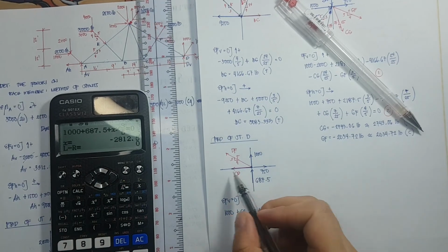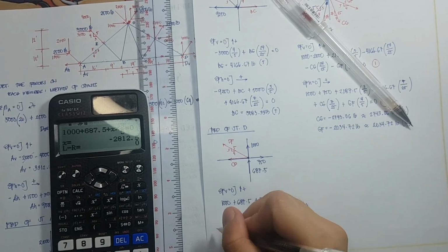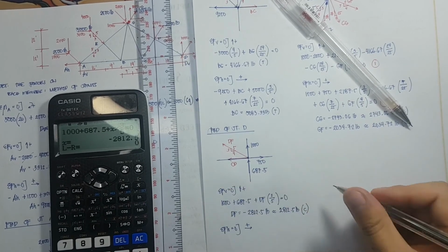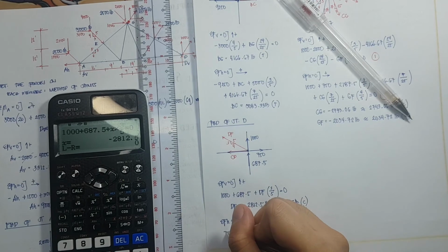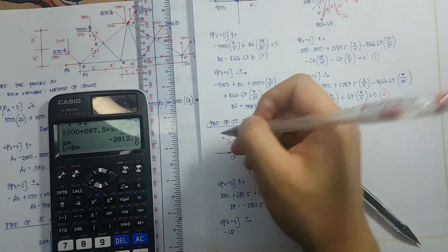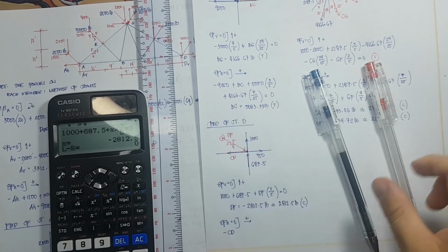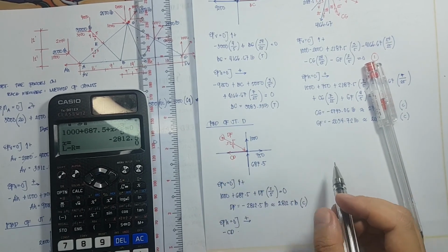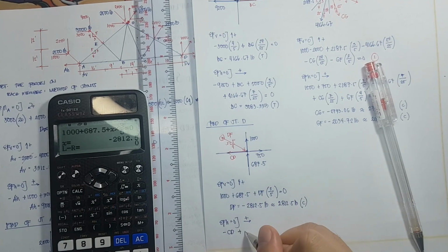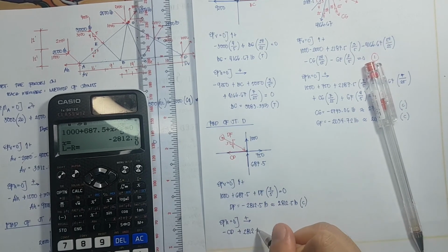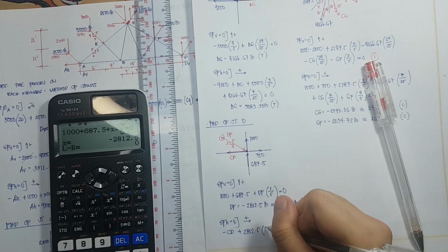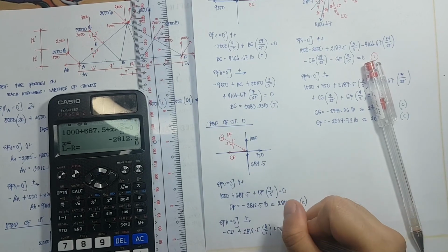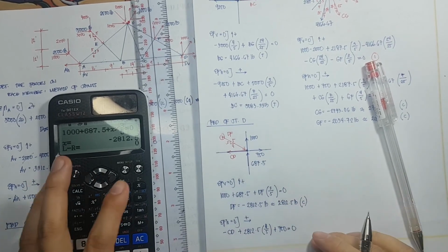Okay, lastly, for the horizontal, for CD, we have summation of forces horizontal is equivalent to 0. All forces that are pointing to the right should be positive. So we have here negative CD. This should be compression. So we have there, what is DF? It is towards right, therefore it is positive, plus 2,812.5 times the horizontal component of 4 over the hypotenuse of 5 plus 750 is equivalent to 0.